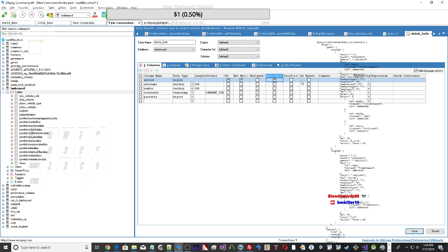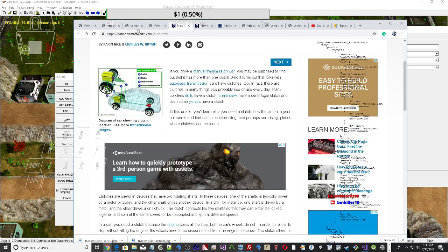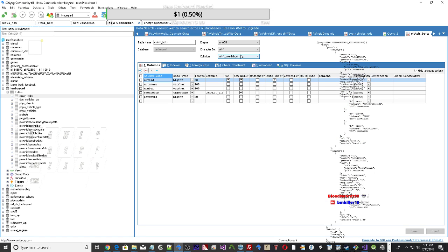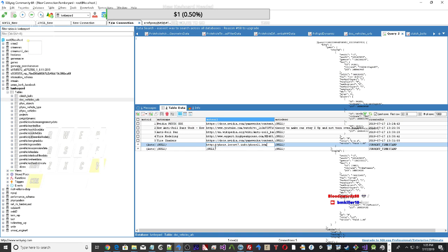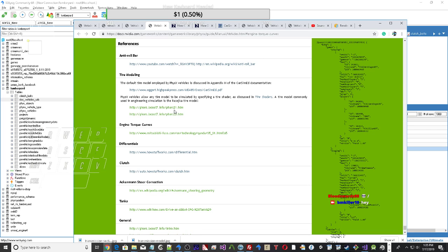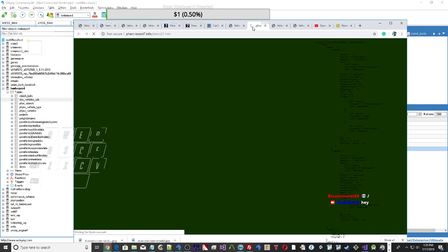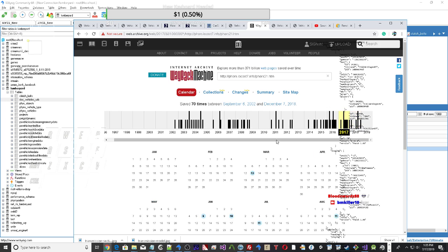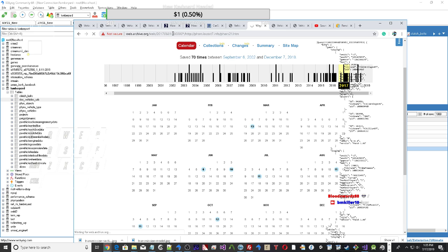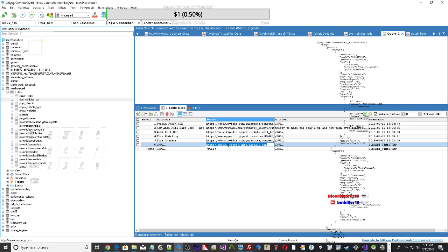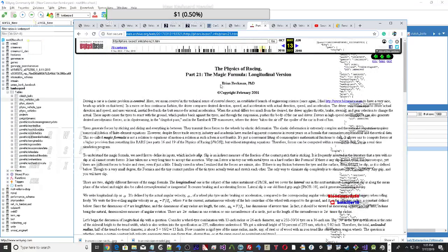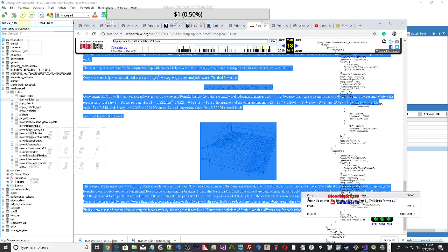Set the camber angles. const PxF32 camberAngleAtRest = 0.0; const PxF32 camberAngleAtMaxDroop = 0.01f; const PxF32 camberAngleAtMaxCompression = -0.01f. for (PxU32 i = 0; i < numWheels; i += 2) { suspensions[i + 0].mCamberAtRest = camberAngleAtRest; suspensions[i + 1].mCamberAtRest = camberAngleAtRest; suspensions[i + 0].mCamberAtMaxDroop = camberAngleAtMaxDroop; suspensions[i + 1].mCamberAtMaxDroop = camberAngleAtMaxDroop; suspensions[i + 0].mCamberAtMaxCompression = camberAngleAtMaxCompression; suspensions[i + 1].mCamberAtMaxCompression = camberAngleAtMaxCompression; }